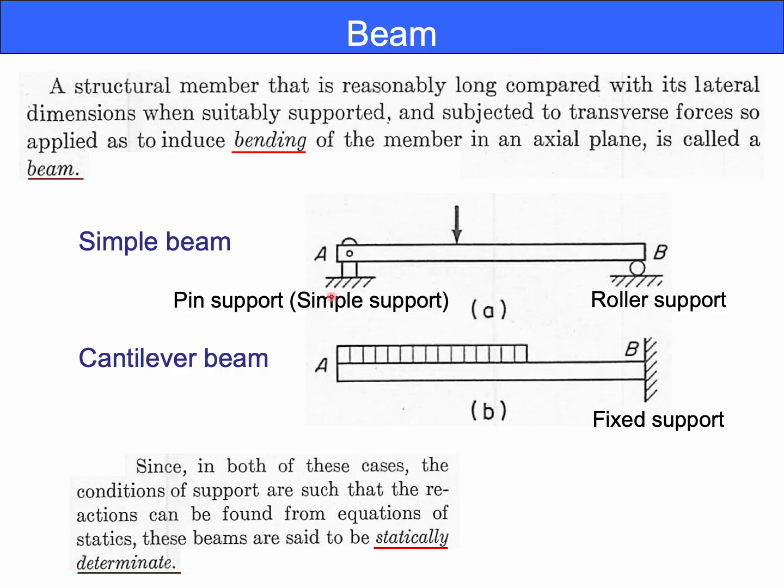Consequently, a pin support introduces two unknown reaction forces, Rx, reaction force in x direction, and Ry, reaction force in y direction.